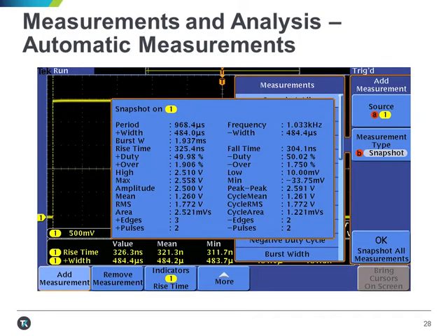Automatic waveform measurements let you take numerical readings based on the waveform. Some form of automatic measurements is available on most scopes, but the range of capabilities varies quite a lot. Measurements often include time-related parameters such as pulse width, period, frequency, rise time, amplitude, related parameters like min or max voltage, peak-to-peak or RMS voltage. Some oscilloscopes can give statistical measurements like histograms or even jitter and eye pattern measurements.